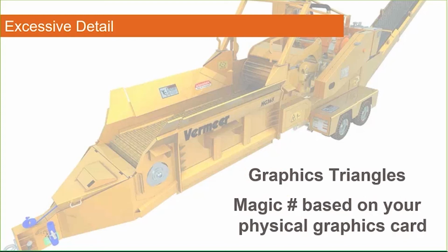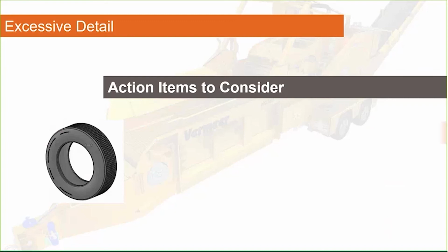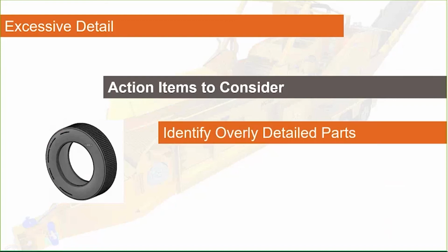I found that my threshold is probably right around a couple million triangles, where I start seeing a sudden degradation in performance when I'm using my assembly. And I only have a video card in my machine that has a gigabyte of onboard memory. So that's kind of a hit and miss target, but you'll figure that out based on the hardware that you've invested in.